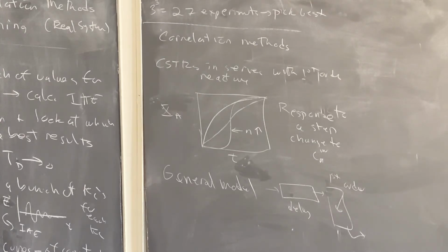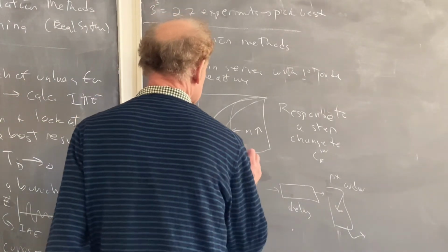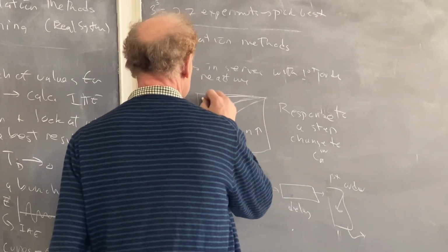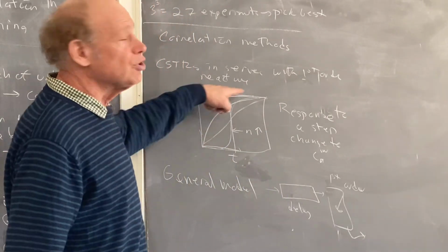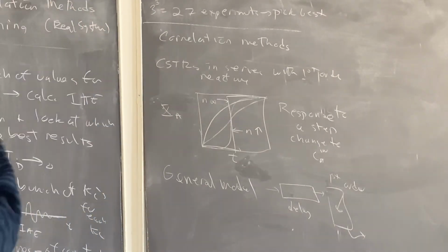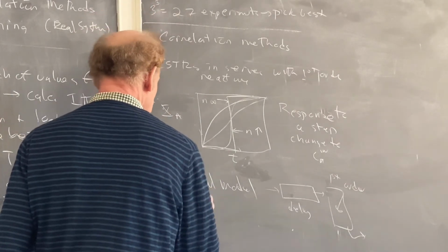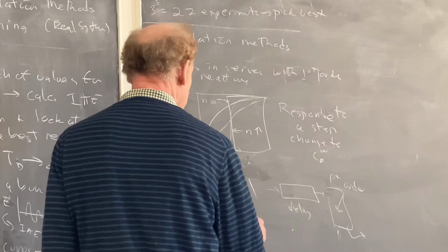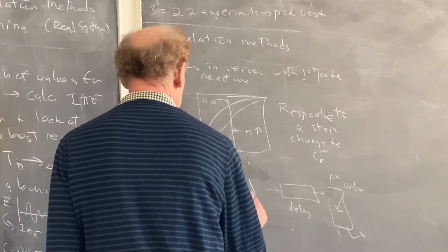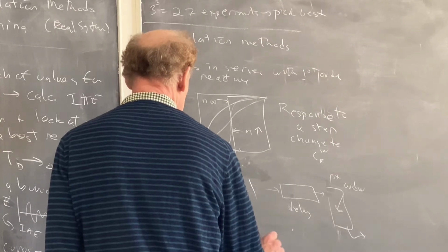Again, the motivation here is that if I had only a first order process, then the delay would be 0, no problem. If I have a higher order process, there's a delay before things happen. It's not a perfect delay. If I had a perfect delay, then it would look like this. But it starts to look more and more like a delay with more and more CSTRs in service. So, in other words, GP tilde, or GP, we can approximate by KP e to the minus S theta over 1 plus S tau.